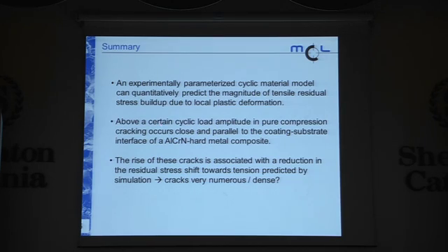And if you have a certain cyclic load amplitude in those structures that I showed you, even in pure compression, you can, of course, if you have a notch, trigger tensile residual stresses and have cracks parallel to the interface. Well, and these residual stresses, if they're reduced to a certain level, you may think that there are cracks involved. We found those cracks, and we think that there must be rather numerous to provoke this effect.